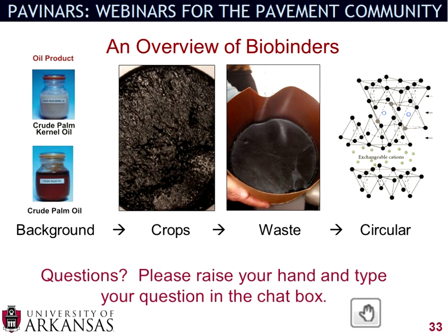The next question is: these biomaterials have a natural tendency to degrade in time, and can I comment on that aspect? I think that's a good question, and I think that's one of the reasons why some of the researchers were looking to have these anti-oxidative effects on the asphalt cement, because at the end of the day, one of the biggest problems with asphalt cement is that it oxidizes and becomes stiff.